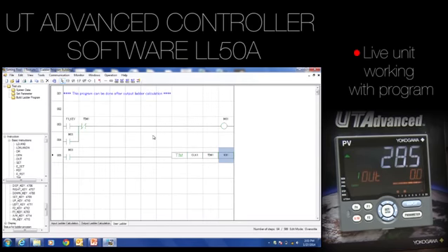So this is going to come on, M01. M01 comes on. Timer is going to count. It's going to count down from 10 to 0. When that occurs, we're going to turn that off. So the other thing I might want to do here is, well, we got that flashing light there on the front, so we want that to run for the 10 seconds. So let's add one more. Let's make this M02.